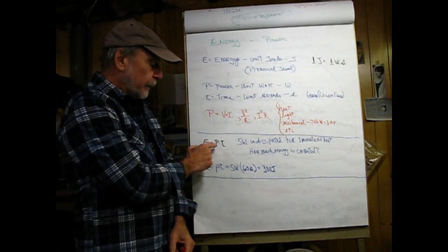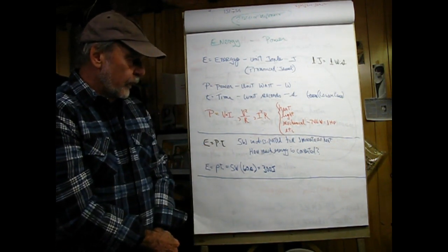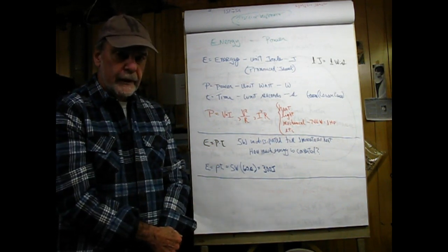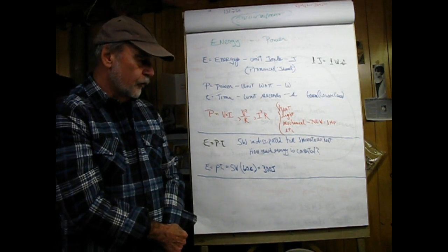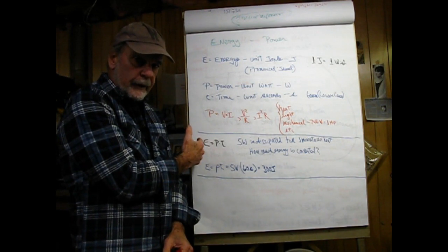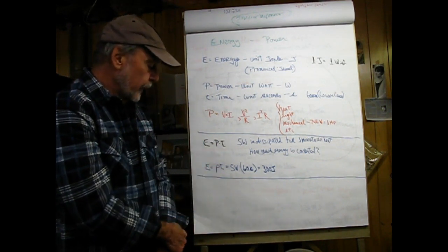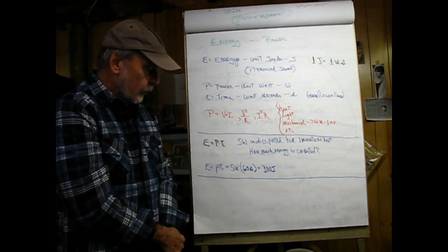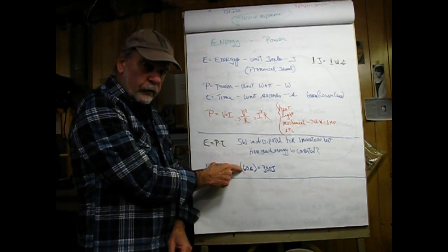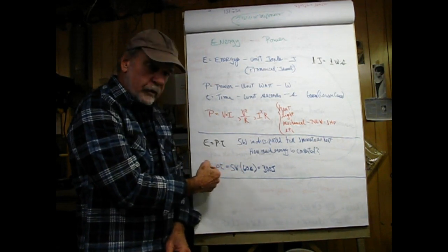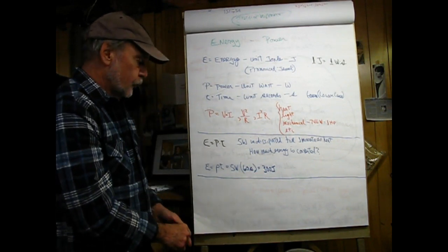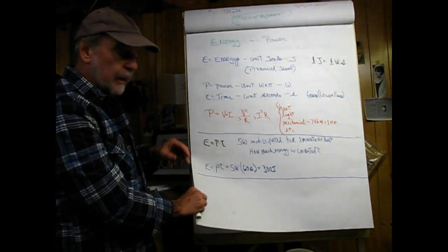So energy is equal to power times time. So if we have 5 watts dissipated for 1 minute, and say we're producing heat, how much energy is converted? So we're converting electrical energy coming into our house, we'll say, to heat. And all we have to do is multiply this out, but what we have here is to convert the 1 minute into seconds. So we'll be doing this in detail later, but that would amount to 300 joules of energy. So it's just power times time for energy.